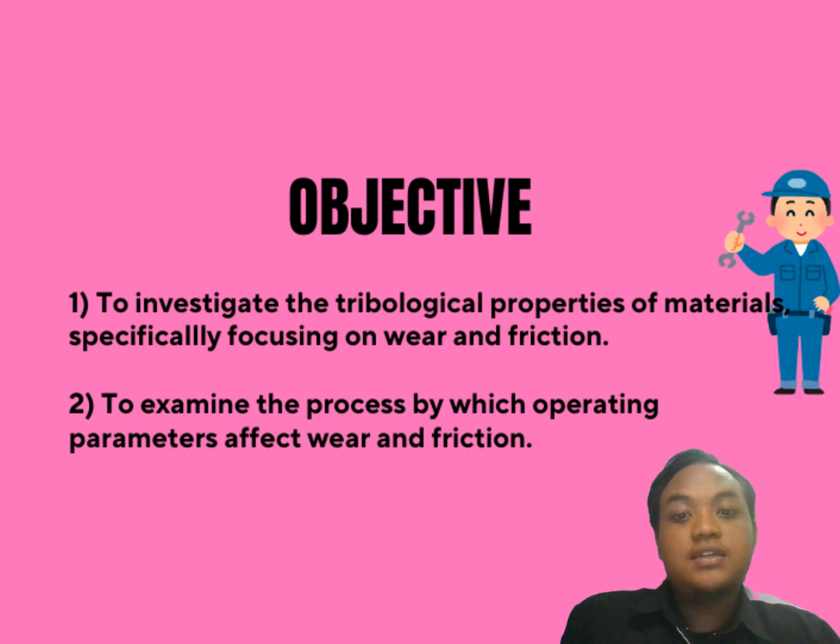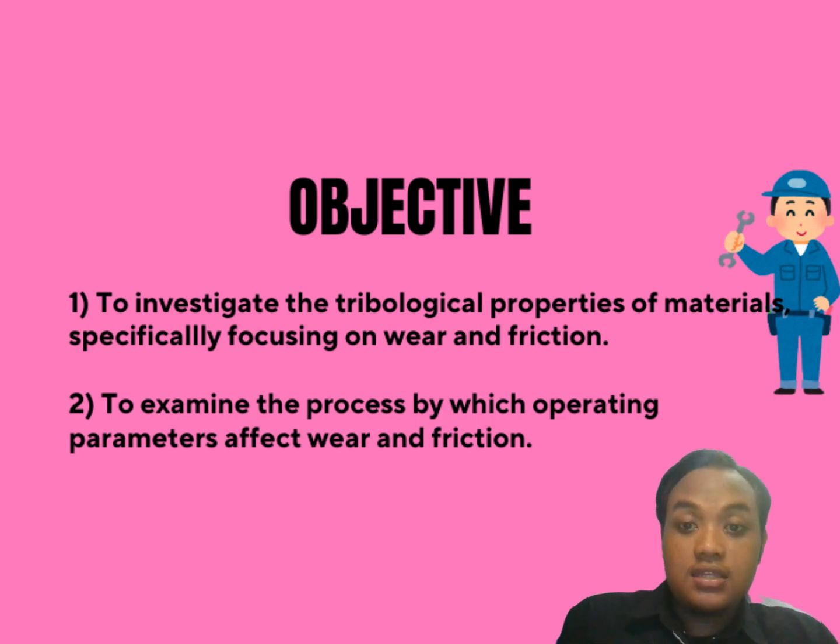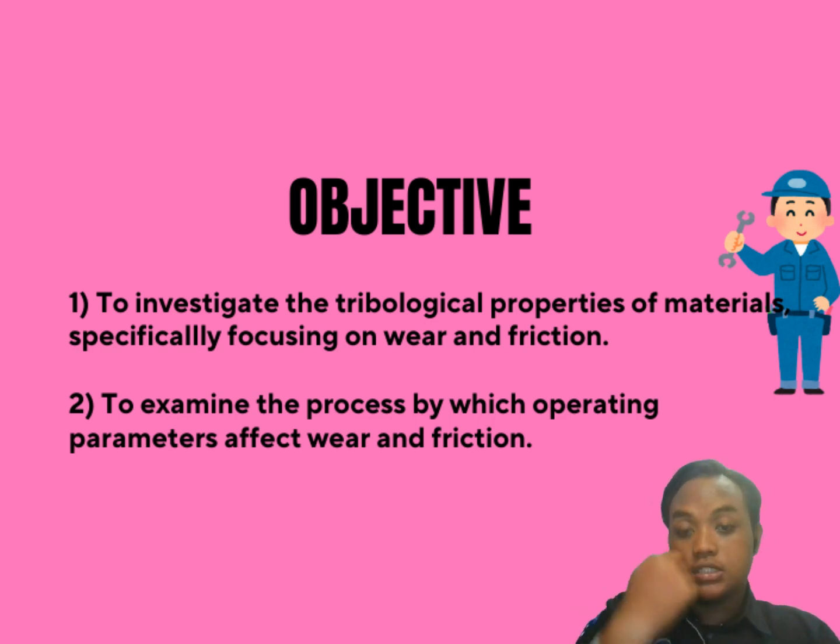The objective of the pin on disc test in a laboratory setting is to evaluate the tribological properties of materials, specifically their wear and friction characteristics. This test involves sliding a stationary pin against a rotating disc under controlled conditions to simulate real-world contact wear scenarios.